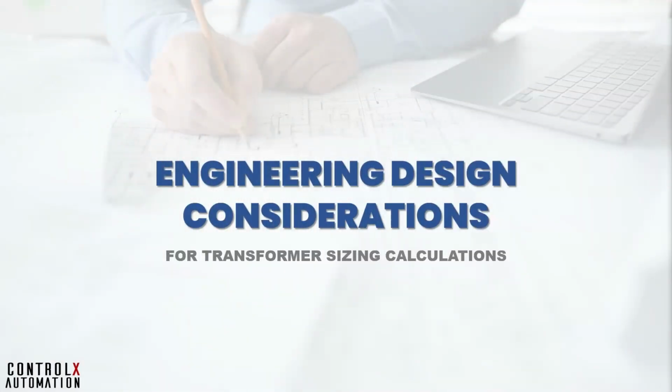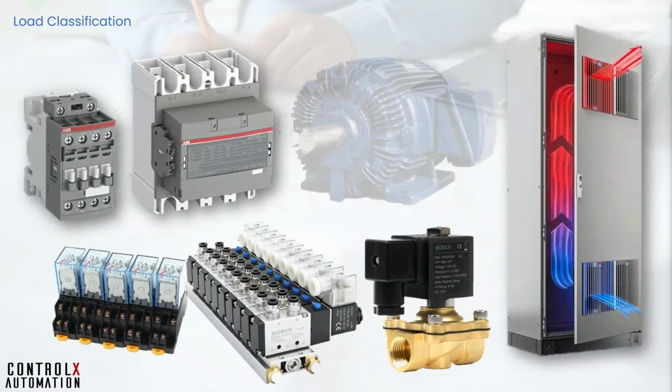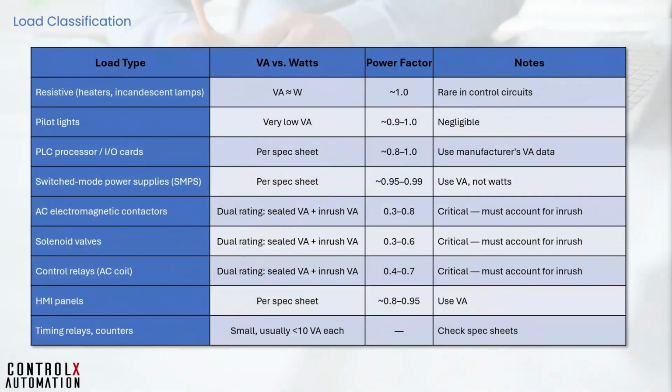Alright, now let's get into the fun stuff. In this section, let's look at some of the key engineering design considerations when it comes to sizing a control transformer for your application. Since control transformers are mostly used with industrial control system applications, the loads it will be serving include electromagnetic components like contactors, relays, solenoid valves, climate control devices like air conditioners, blower fans, pump motors, and the like. Before sizing a transformer, classify every load connected to the secondary. Always use the load's VA rating and never watts for transformer sizing. A power factor of less than 1 means the transformer must supply more apparent power than the load's real power, as we have seen earlier.